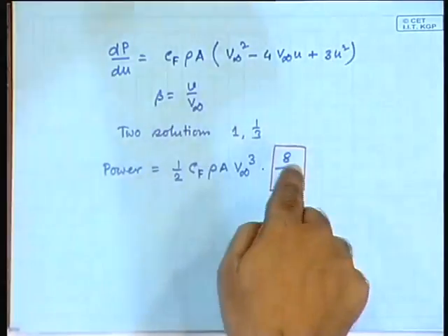Notice the line of argument. First we said that let there be a slit through which the wind is passing and we have some kind of a converter that is extracting that energy output, and we proved that the maximum possible efficiency is 16 by 27. Then we said that no, let us now think in terms of the existing wind turbines, not today's, but existing at that time, which operate on thrust, and there we obtain that it must be less efficient. So, there has to be some other principle of operation completely different from the thrust principle.